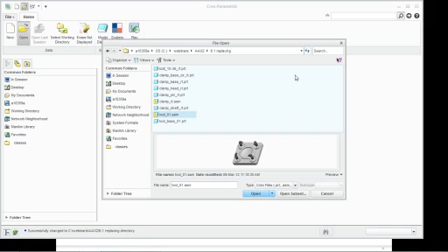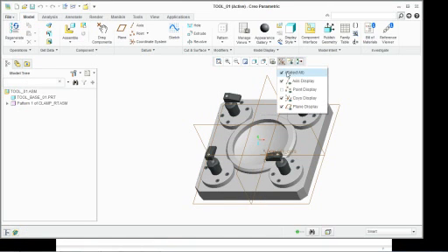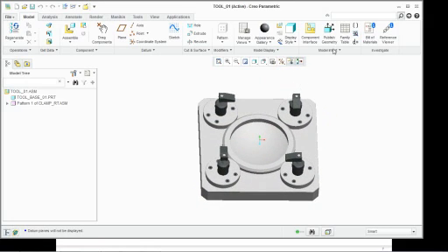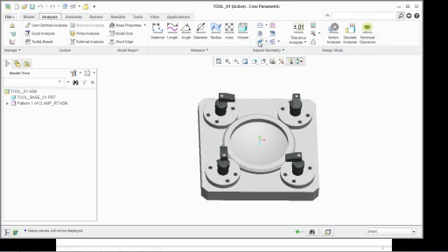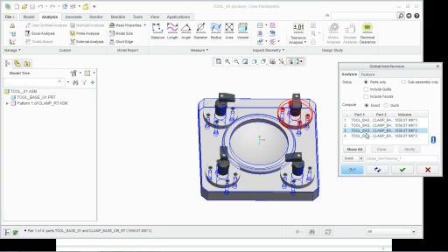First, I'm going to show you how to do some component replacement. We're going to open this assembly. Let's say this is something that we've designed. Turn off my datum features there. And right at the end, you go in and do, let's say, an analysis, and we're going to do a global interference check. So we're going to preview this, and we notice that it's interfering in 4 places.